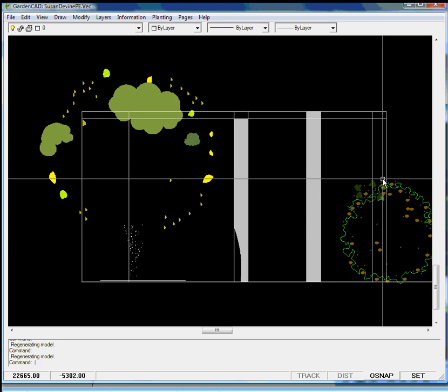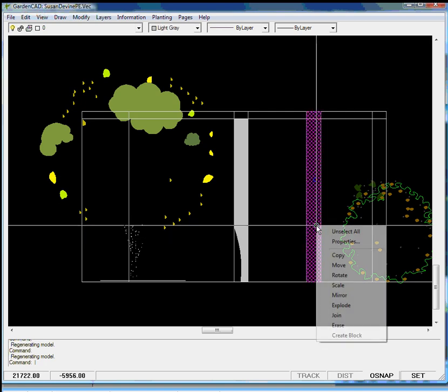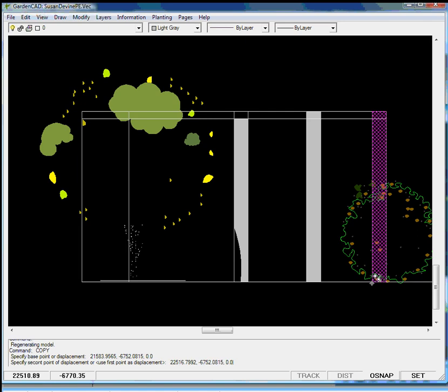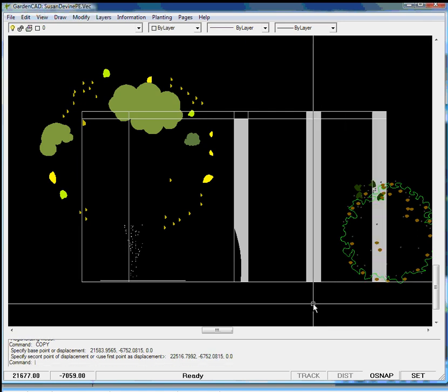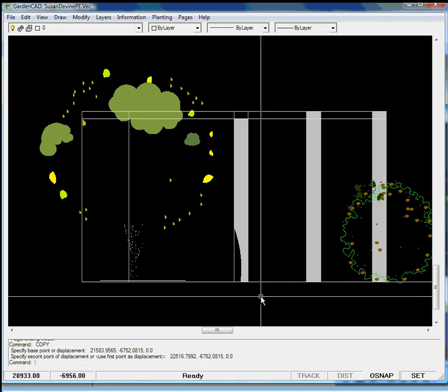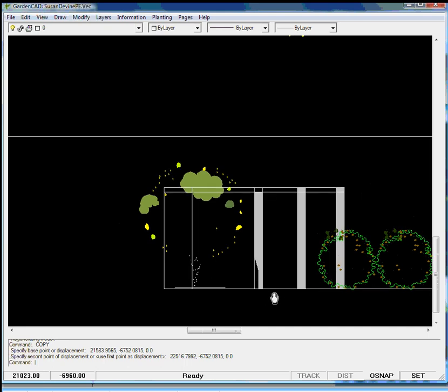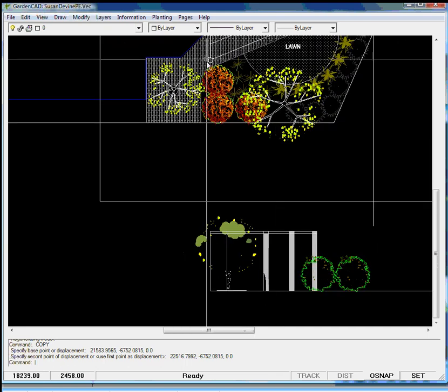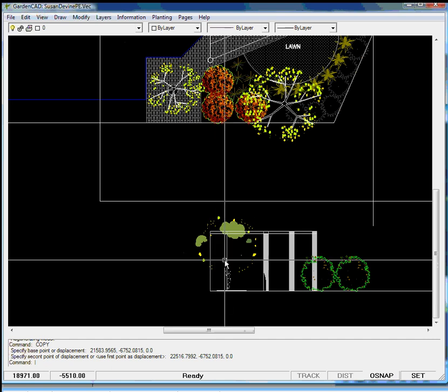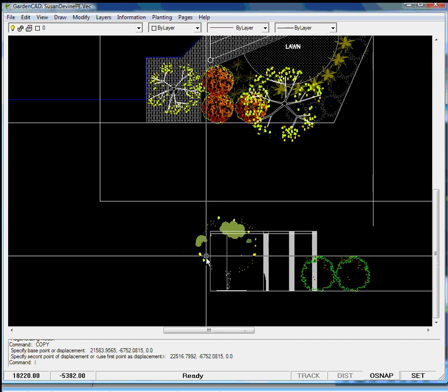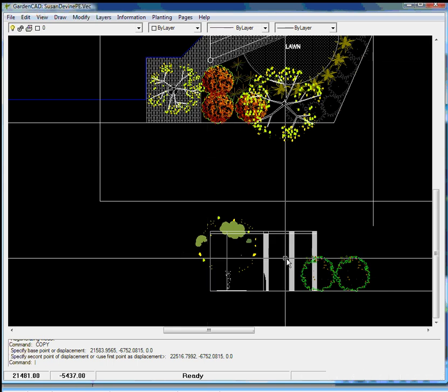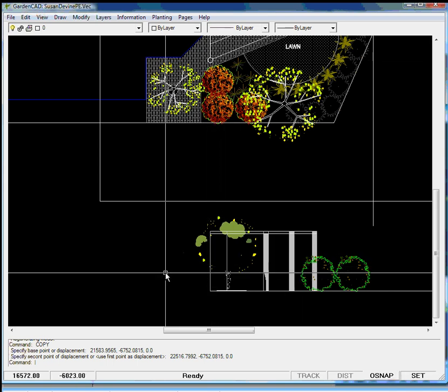Now since this pole is identical, there's no reason why you couldn't click on that, right click, copy, snap to that point there and come across there and do that, and the next pole is in. So I'll just zoom out a little and pan down so you can see we're building our elevation of the zone through there. We've of course got to get another pole in this position here, and I've dropped a line from the outside there, so I need to move that pole to the inside of that line, and you should be able to see that's relatively easy to do.